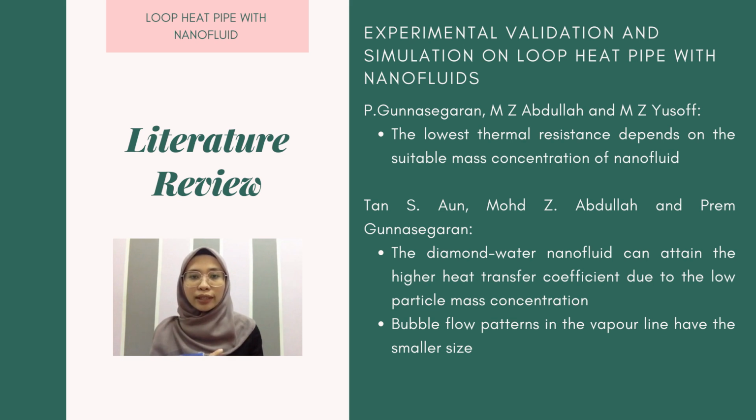The experiment to analyze the heat transfer performance and thermal conductivity effects was developed by the researchers Tan, Muhammad Abdullah and Frank Gunasegaran. The diamond water nanofluid can attain a higher heat transfer coefficient than pure water, due to the low particle mass concentration used. The result has shown that the bubble flow pattern in the vapor line has a smaller size with diamond water nanofluid, and it causes a higher heat transfer characteristic in the loop heat pipe compared to using pure water.